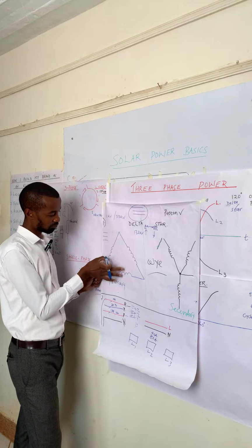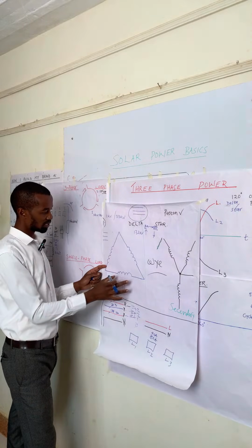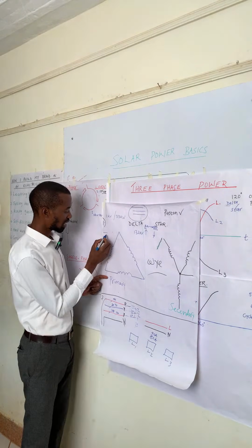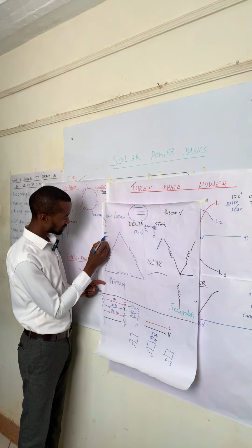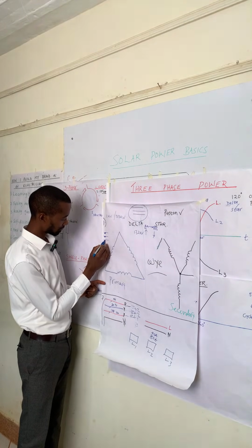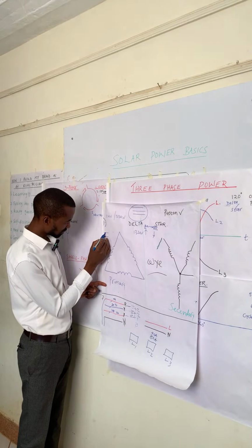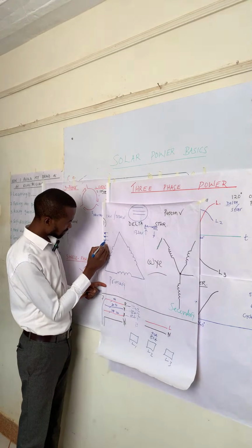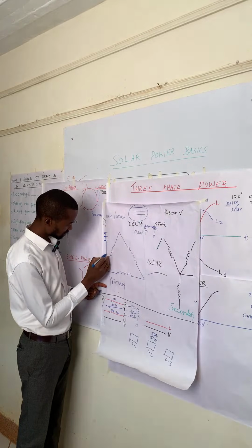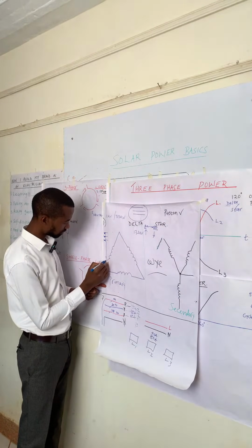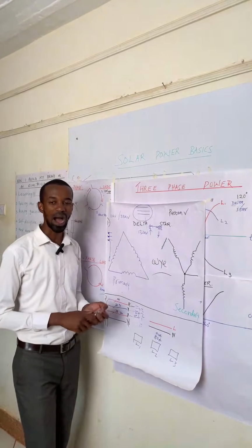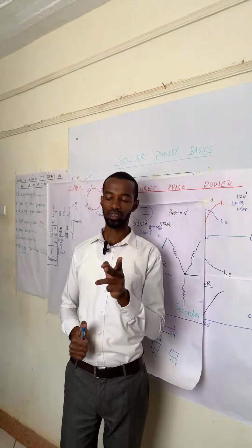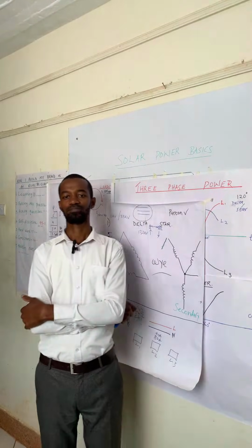Another issue is if it strikes on the primary lines or primary conductors that are feeding the transformer, especially in this case on the delta connection. We normally have something at the transformer that is referred to as surge diverters. These surge diverters are connected and then earthed. So at the transformer level it is very rare to have such a case unless the earthing is compromised.